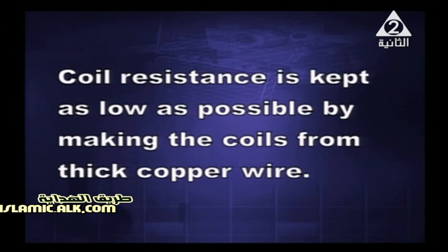Coil resistance is kept as low as possible by making the coils from thick copper wires. So the coils should be made of copper. Why? Because it has low resistance, to reduce the loss of power in the form of heat. Okay, this is one loss.